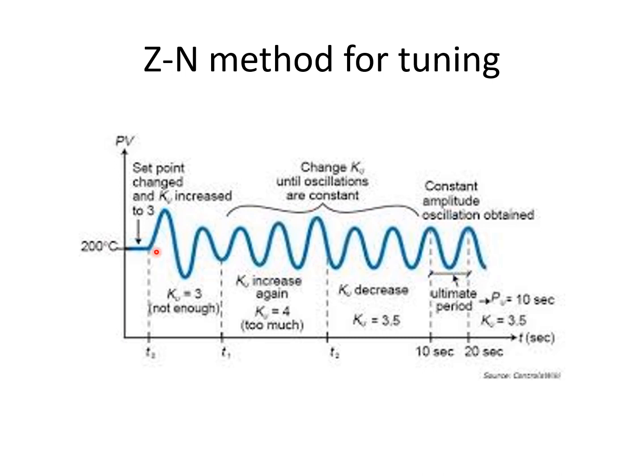Increase a set point change, or you can also use a disturbance rejection case, but normally you try a set point change and try to get this oscillation. And once you get the KU, the ultimate gain, the P tuning or KC tuning that gives oscillation, you also get the ultimate period here. So you can calculate from here to here, at different points, but this is the easiest to see.